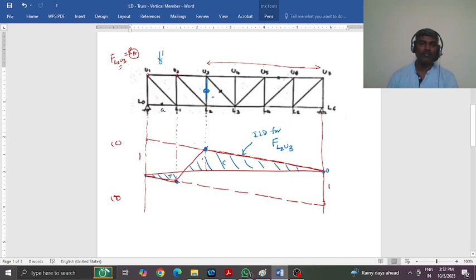And what are these values and how do you get them? Let us say this is span A. From similar triangles, as this is 1, this will become 1 by 6. This is 1/6 of the value, right? And how do you get this value? Again, from similar triangles, it is 4 by 6, since you have 4 spans here.